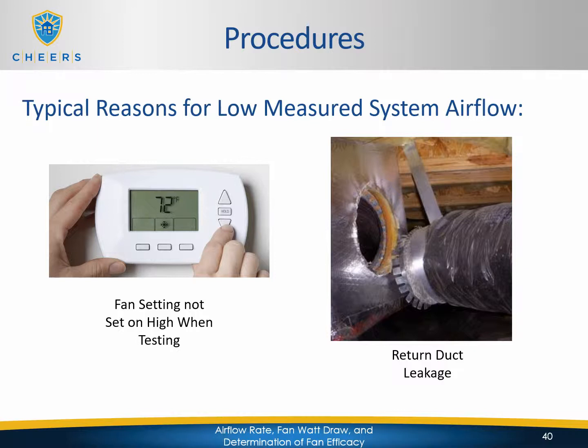So if you're below 60 degrees and testing for this particular test, meaning that you'll be turning on the cooling system, which is the highest speed setting for the system, pull the disconnect on the condenser first so that the blower will run at the highest speed, but the condenser will not kick on. And then obviously remember to turn it back on when you're done with the test.